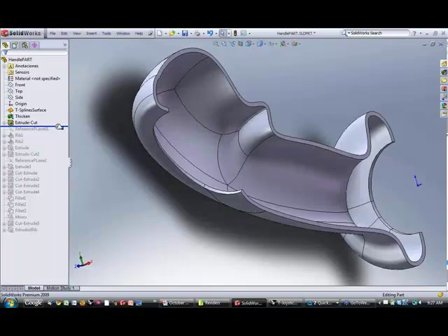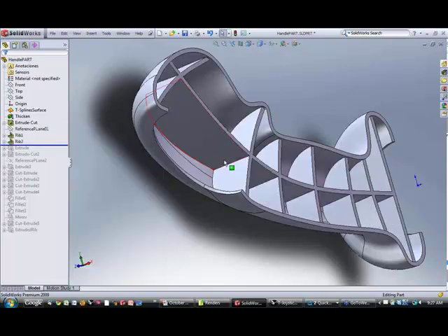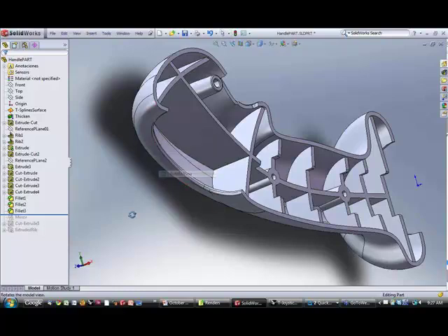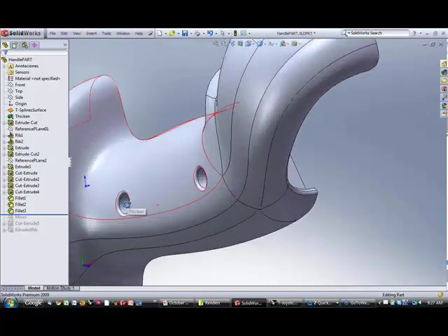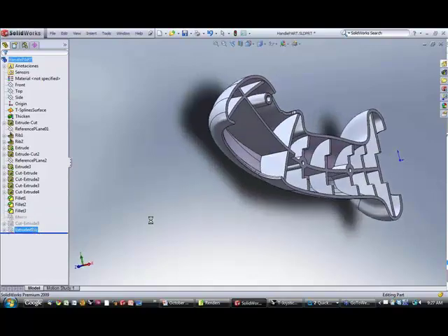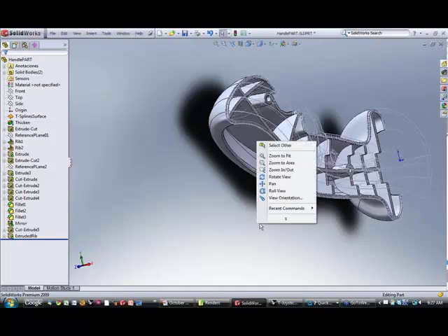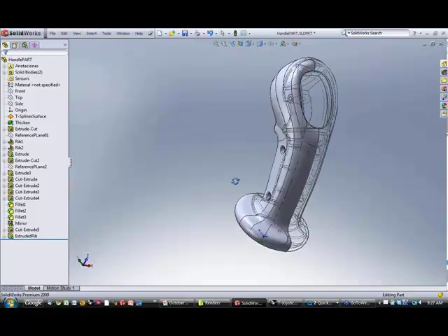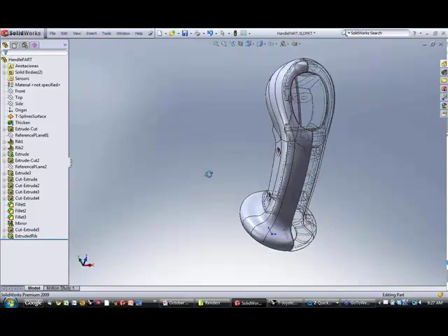We can cut away at the model. We can add some ribs, perform some extrusions, some additional extrusions, add some fillets to the model. Let me rotate just to show how those fillets are being applied over here on the opposite side. And just treat it like any other geometry inside SolidWorks. So now we have that nice organic T-splines base of our SolidWorks model.